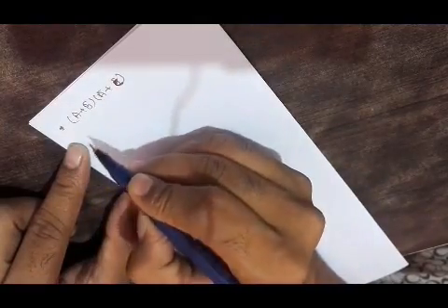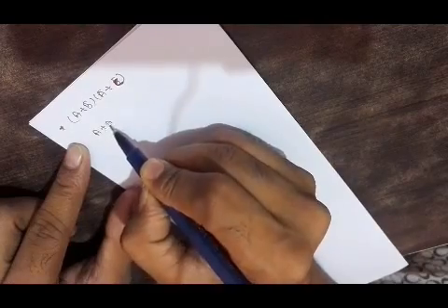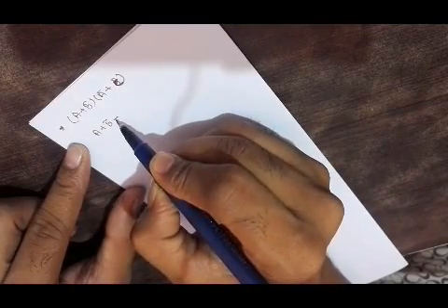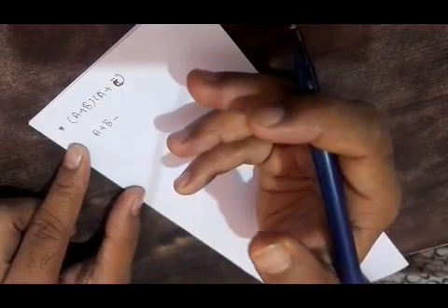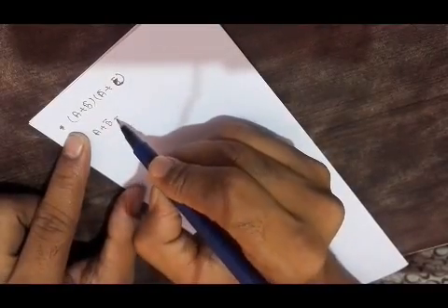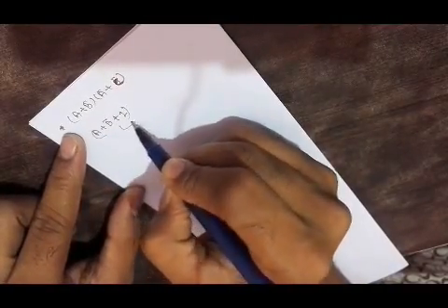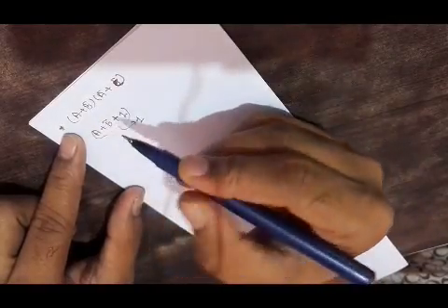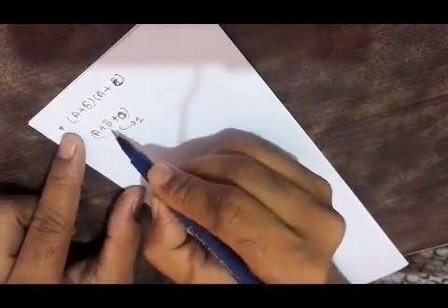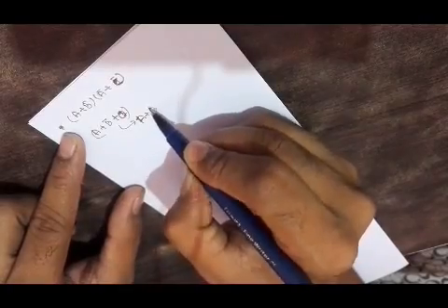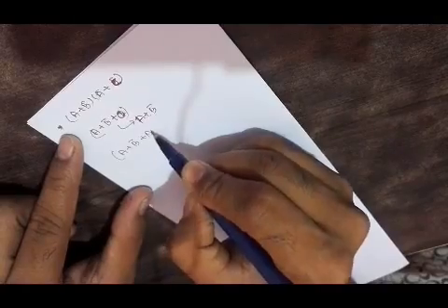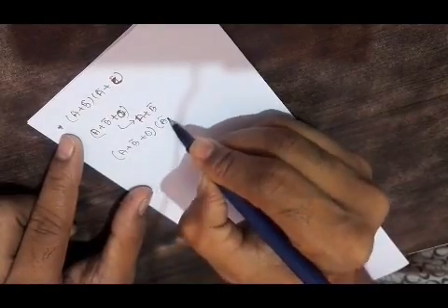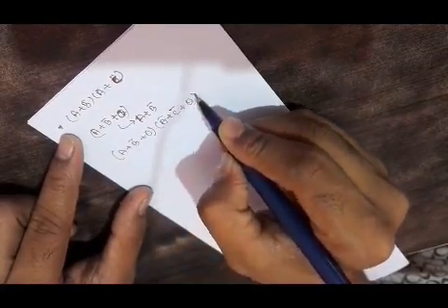So what can we do now? This is A plus B bar, and we know that if we add 1, what will this term become? This term will become 1, so it's going to change. If we add 0, this term will remain the same. A plus B bar is the output. So what we can do is A plus B bar plus 0 over here, and then we have A bar plus C bar, and we can add 0 over here.